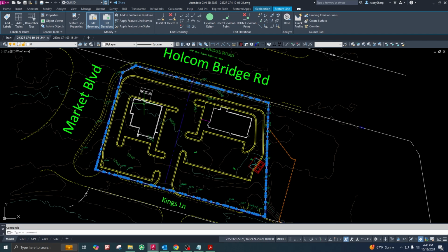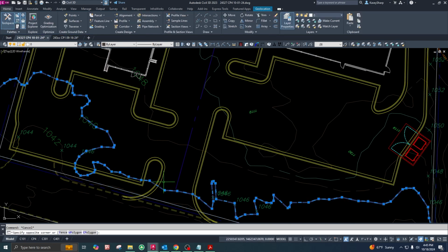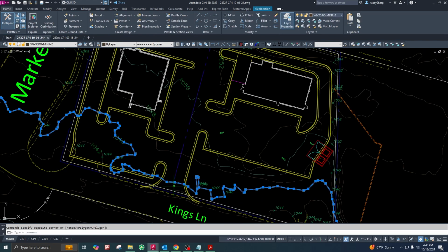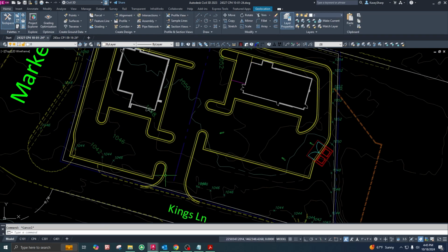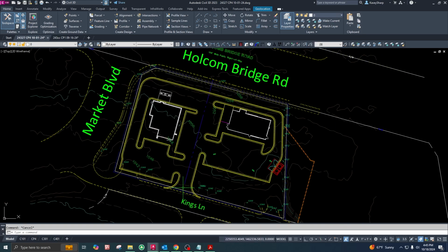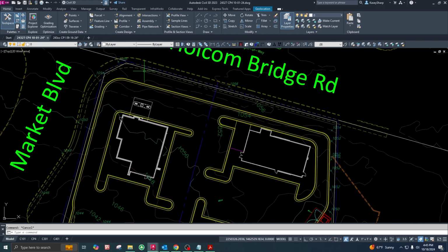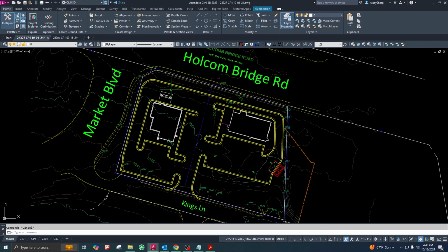So along the length of this feature line, we don't want to change the elevation at all. We want to leave that at whatever the existing grade is. So probably what we'll do is have this guy slope up a little bit more on this drive, maybe a little bit steeper right in this area, closer to 10% or 5%, so that it flattens out here. We don't want to have a wall here, but if we did need a wall, we have space for it along the top here and not really along the bottom. So I'm thinking we're going to set our FFE, it's going to need to be higher than the surrounding area so that all the water drains away from the building.